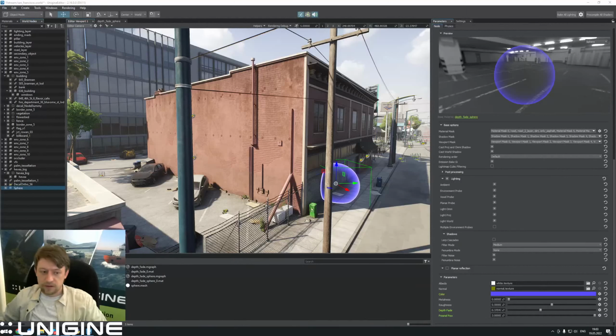Right now, the easiest way to create a car paint, for example, is to use doubled geometry for the whole car, which is painted, and the upper geometry will be transparent in an additive mode, and you will have two different BRDF, so basically two different highlights, and it is actually how car paint works. So it's just not very convenient to create it.